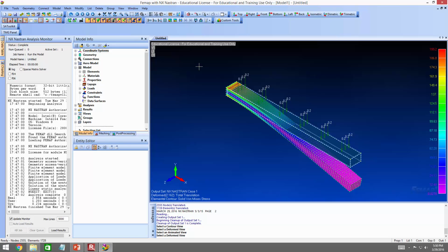Now, one thing that's kind of nifty, if you look right here, do you see these two boxes right here where it switches contours to previous and next? If you start clicking those, you'll see your contour changes quite a bit. Y'all see that? If you look down here, what's happening is you're switching to a different type of stress calculation. So this is solid shear stress in the XY plane or what have you. So this is like the shear stress in the beam, or stress along the Z direction. There's not much at all. But if you notice, what was the very first one that it printed out? Von Mises. Told you this stuff was important.